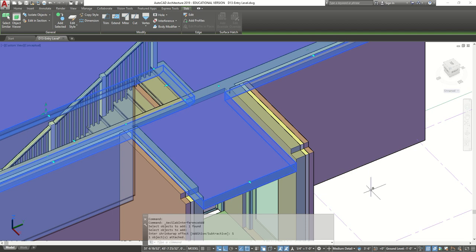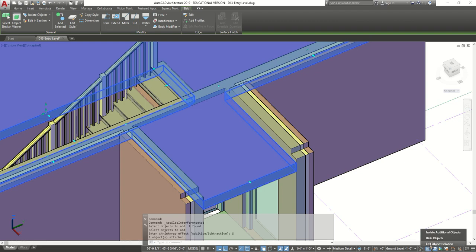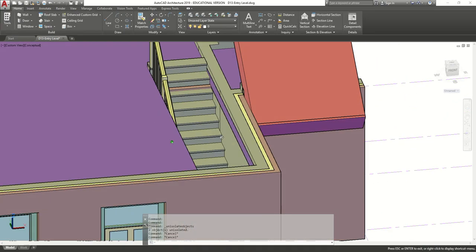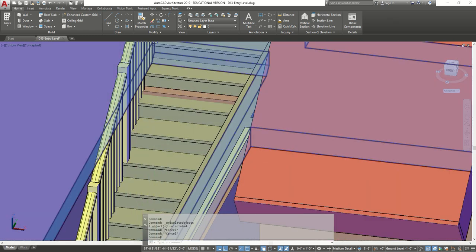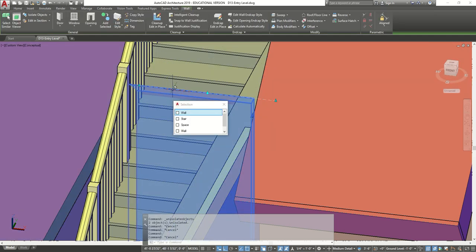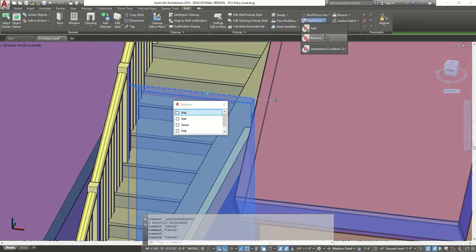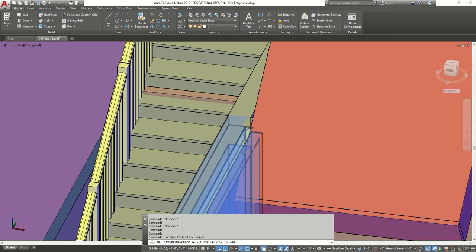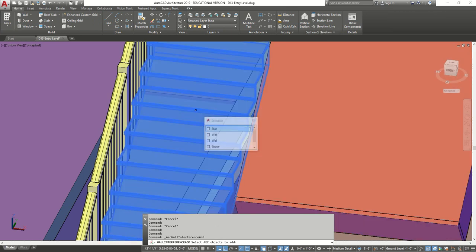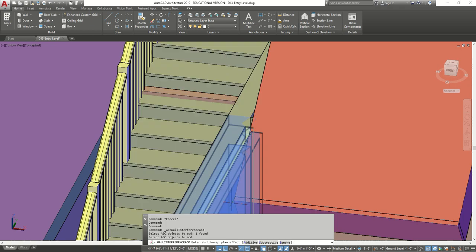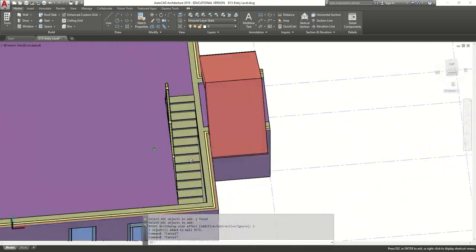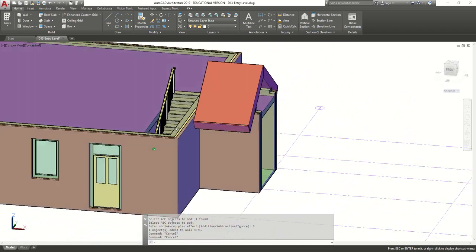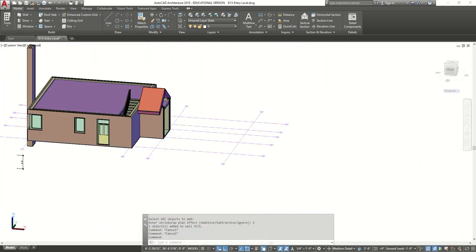Alright, now we're going to go back to the corner here and do end isolation objects. And like that, now our stairs are not cutting out. We have a wall cutting through it, so we're going to do the same thing to the wall underneath. Let's just do it again. Interference, add, select the object, subtract. There we go. And we fixed that staircase as well. Good. There you have it. We added the cut out hole, and we are done for this tutorial.